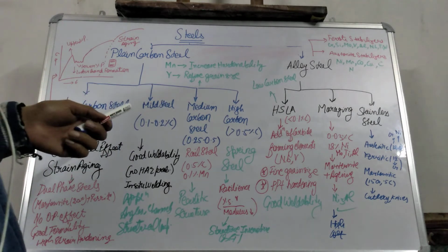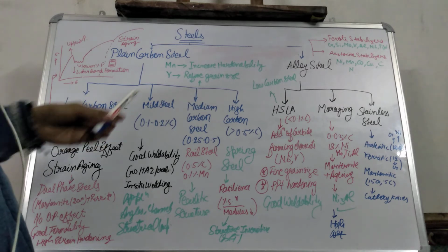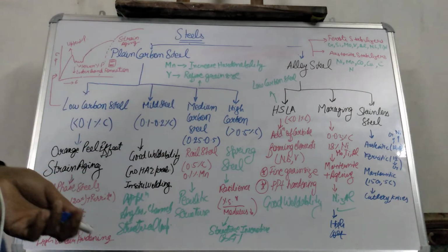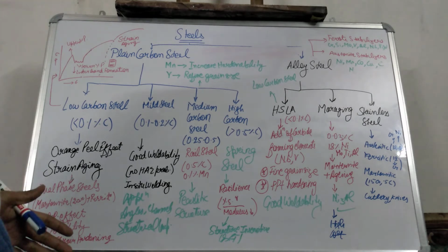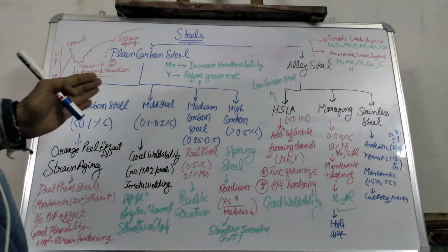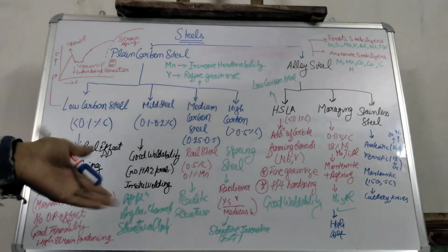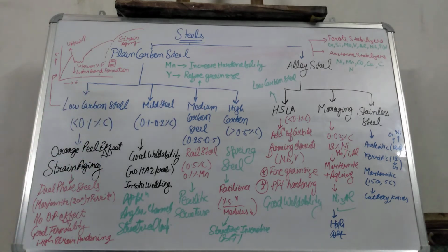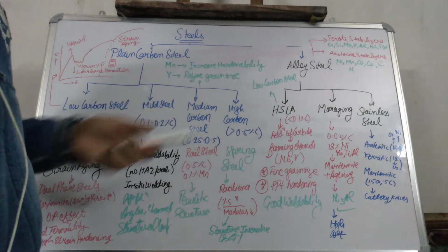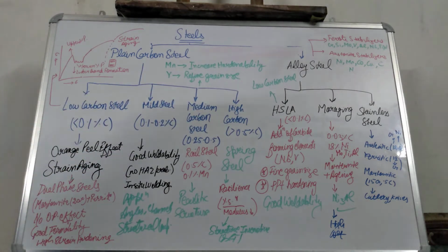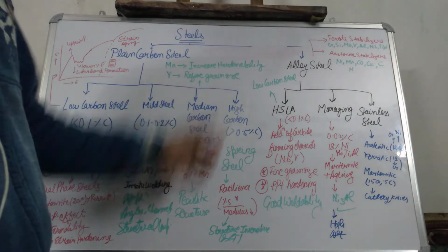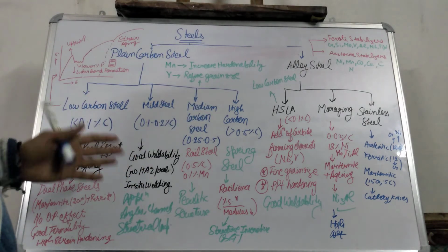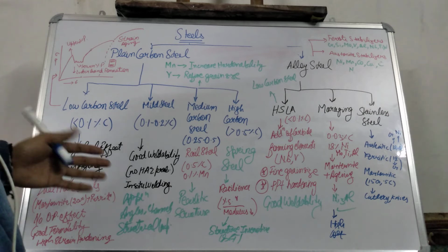One are classified as ferrite stabilizers: they increase the ferrite or delta phase field and decrease the austenite or gamma phase field, and they also lead to formation of a gamma loop. The others are austenite stabilizers: they expand the gamma phase field, and in certain circumstances the gamma phase field extends to room temperature and there is no ferrite formation.